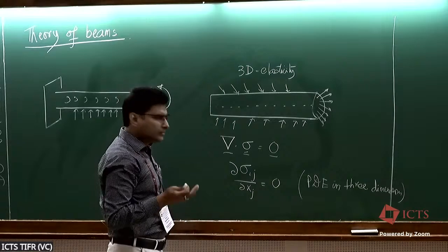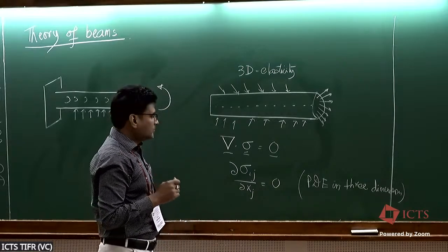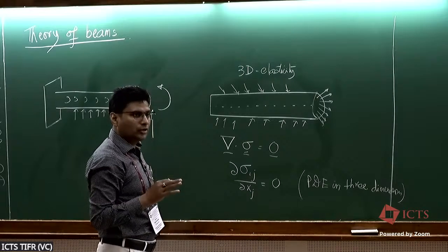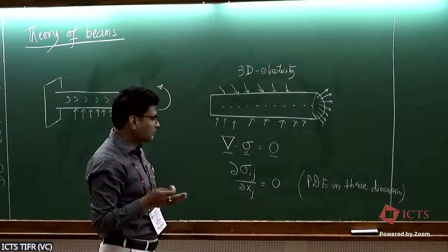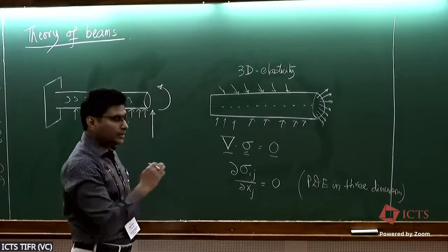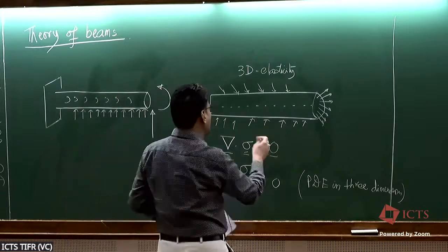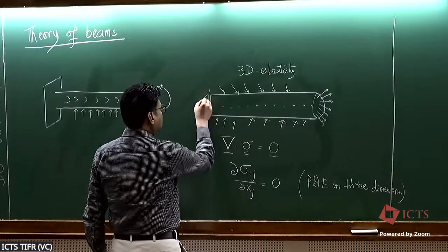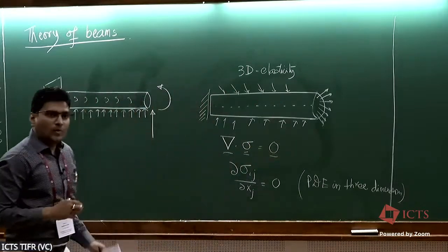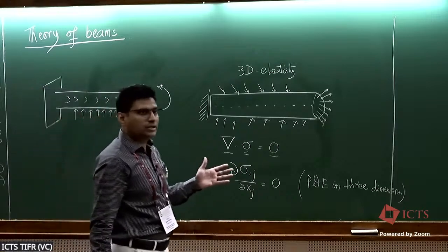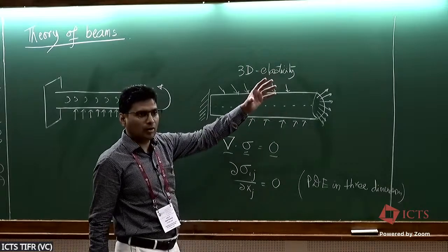And you guys know that PDEs are very difficult to solve. I mean, paper and pencil, really forget about it, right? You have to really resort to numerics to solve a PDE. It's a PDE in 3 dimensions. And of course, you also have to say what's the boundary condition. For example, on this surface, it could be clamped, and then you have traction boundary condition. But if you can solve it, which is difficult, it gives you the full deformation of the body, right?